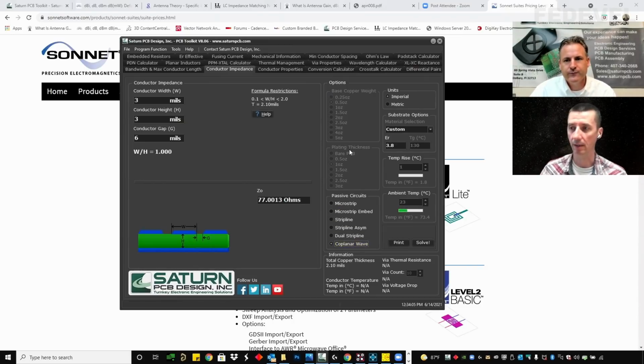This is good to know that it will be there, because I have got some questions, people asking me how to calculate the impedance in this kind of situation when you have coplanar. I do use this calculator myself on my products. I find it to be accurate according to what I've measured. The only problem is that the formula I use assumes a thickness of 2.1 mils. Again, the Waddell formula gives me the option to change that. I just can't get it to work.